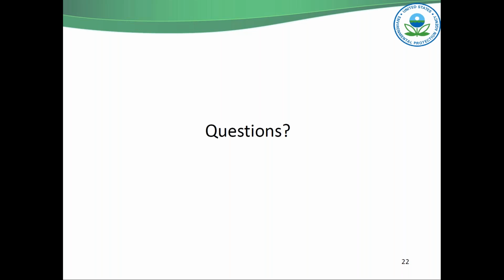So I want to ask a question, and I'll ask you, Kenny, but I'll also switch to Stig to get his answer. Is the issue of aeration for DBP control, and again, I'm not an expert on it, but I know it works better for the chlorinated DBPs, so chloroform and things like that. Strip that out, which will leave the brominated, which will reduce the total number and might put you in compliance, but now you're leaving more of the ones that technically might have the more adverse health effects. Have you seen that in the before and after, or did you get some reduction in all of them, or what's your perspective on that?